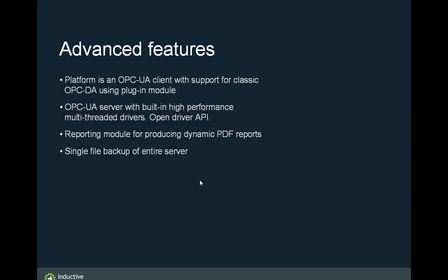Although we do have an OPC UA server and client, you are also welcome to use Ignition with the older forms of OPC, which is the OPC DA servers. So this DA uses DCOM, which is a Microsoft technology. Microsoft has abandoned this technology, but there's still a lot of these OPC DA servers on the market, and we will still work with those. Also, you can have what's called an Open Driver API. So if you're so inclined, we actually open up our OPC UA server so that somebody can actually write a driver for that and use the OPC server for themselves.